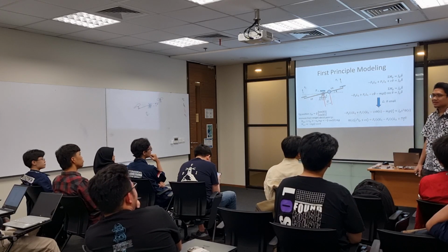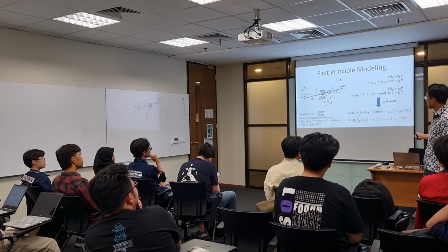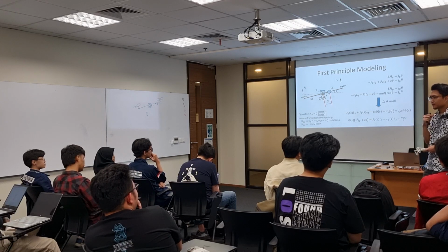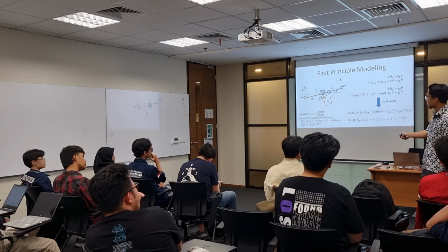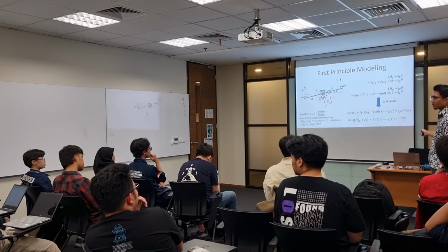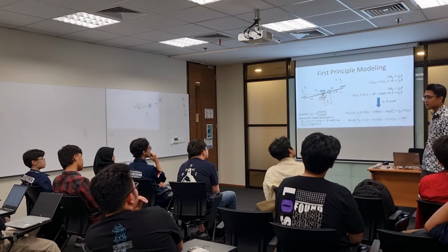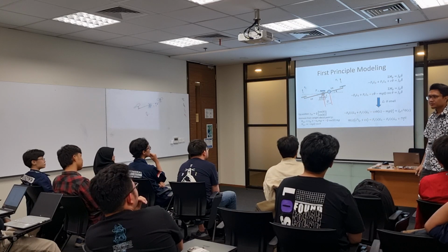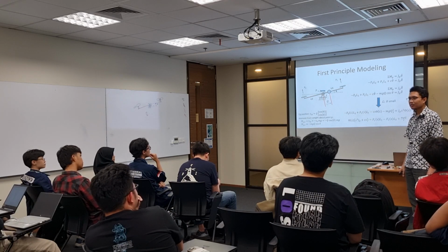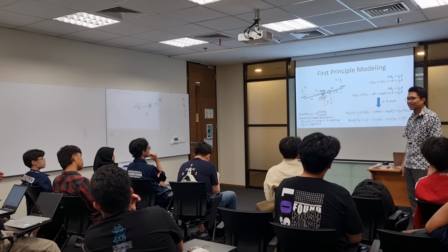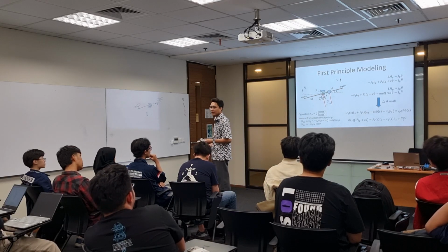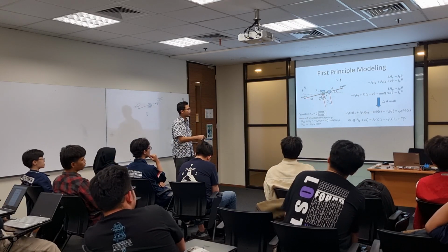Friction, correct. It's friction, not tangential speed. So the C here is the friction coefficient, which we assume to be linear, coming from the bearing. What about this JP? Anyone know what JP is? Something related to mass. No. For linear motion you have mass, but for rotational motion, what do you have? That's correct. Rotational inertia of the whole thing.